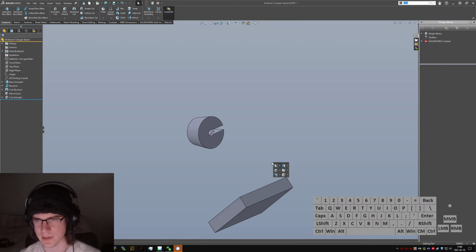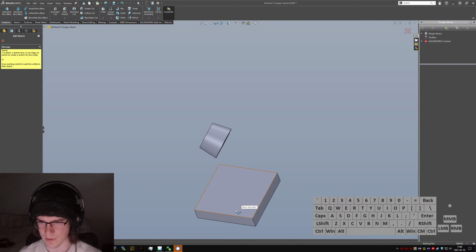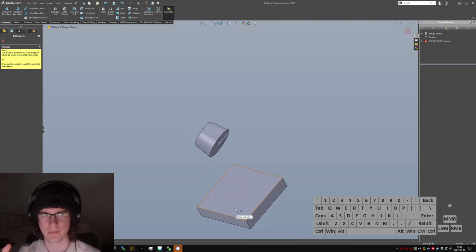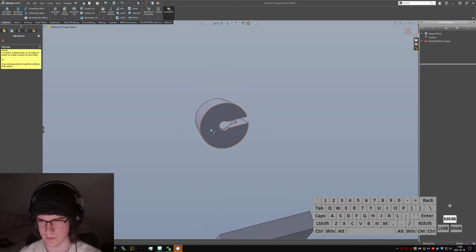Ooh, I just had a really dumb idea that might actually be maybe good. Let's try this. I'm going to put a sketch down here with my desired exit location for the cable on this side, and I'm going to have it built into the loft, so my loft sort of follows what I'm looking for.